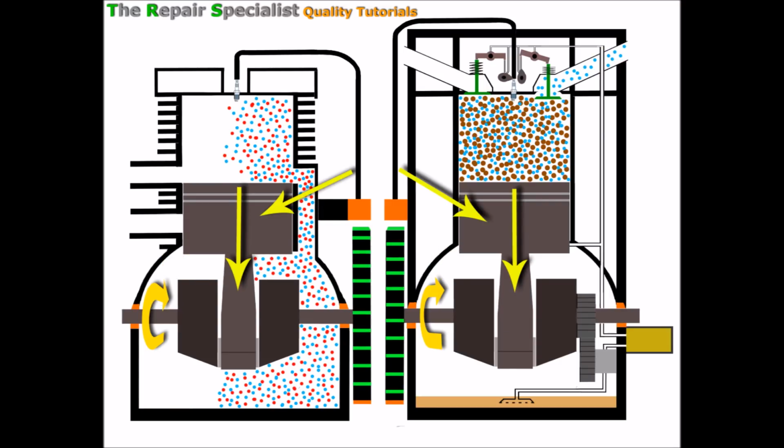Now both pistons are at their lowermost points because the crankshaft has turned a full 180 degrees from the piston's top dead centres. And we can see in the four-stroke here that it continued to bring in that nice flow of fresh air into the cylinder, all thanks to the exhaust valve being opened by the timing of the cam there and the rocker arm. And if we compare all this activity now with the activity going on here over in the two-stroke, then we can see that there are so many differences between the two engines.